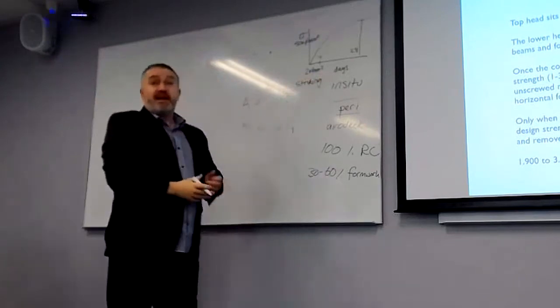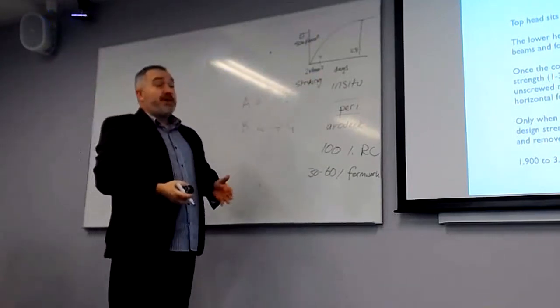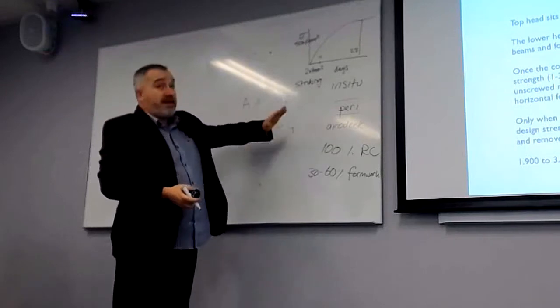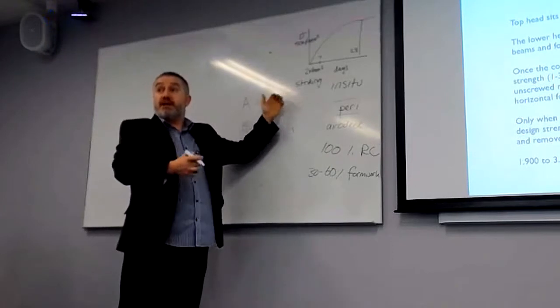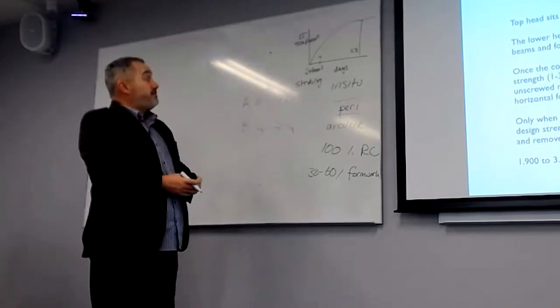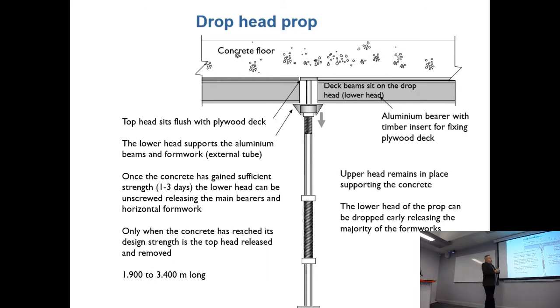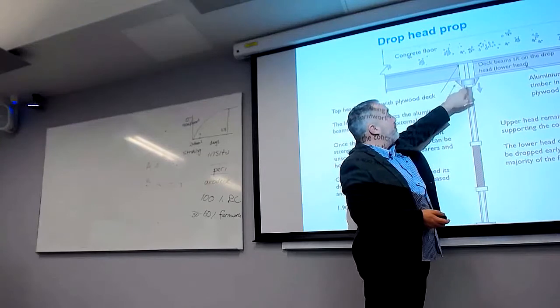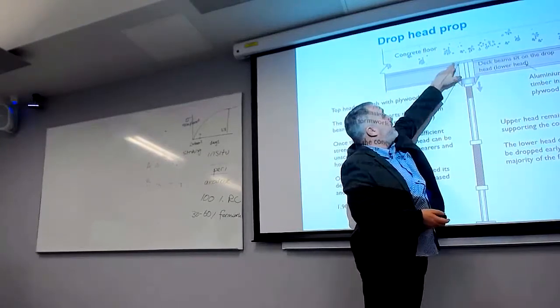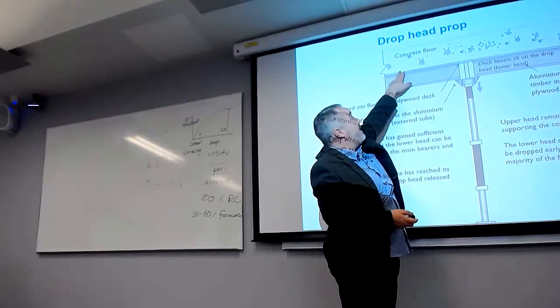I believe the word striking comes from where they hit the timber to free it from the concrete, and then they remove it. And because they're trying to move the formwork around really quickly, they use a lot of these drop head props. So this is our prop here, and the outside of it is holding up the beams, and that's holding up the timber that is connected to the concrete.